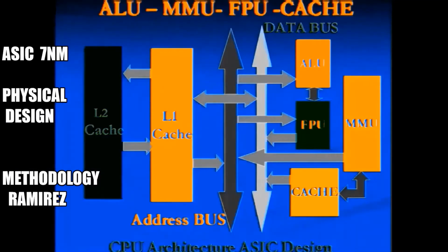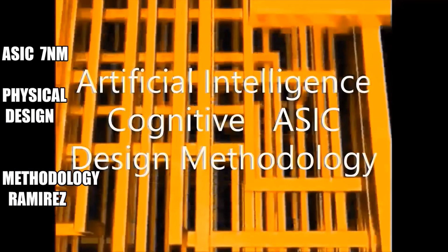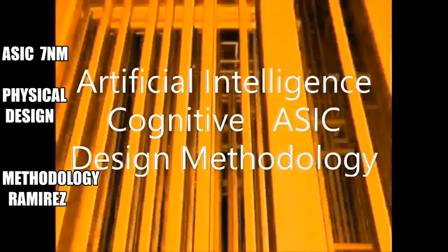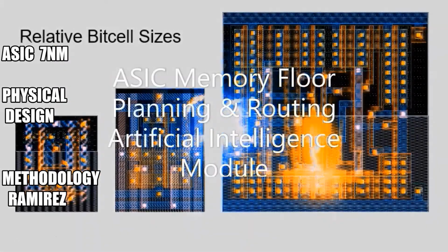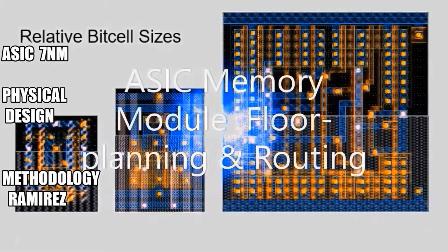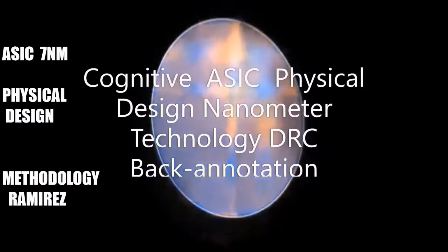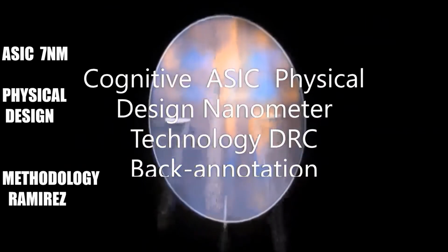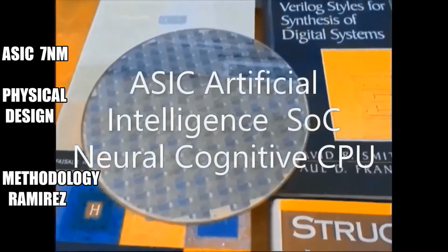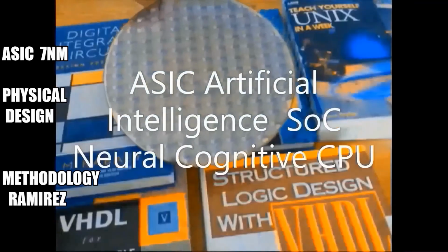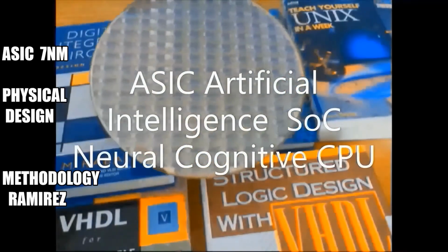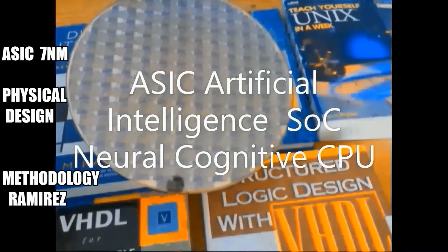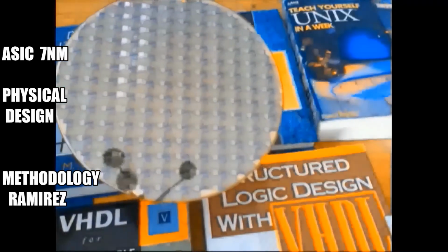On the back-end mode, it generates the SPICE models with layout views and timing models to perform DRC and LVS. It can perform at each level of hierarchy or at the end of the hierarchy and simulates power delay, and it can also be back annotated.